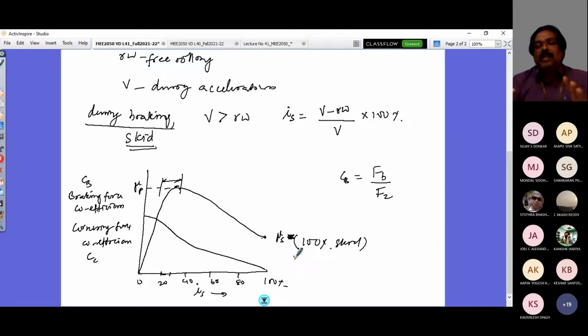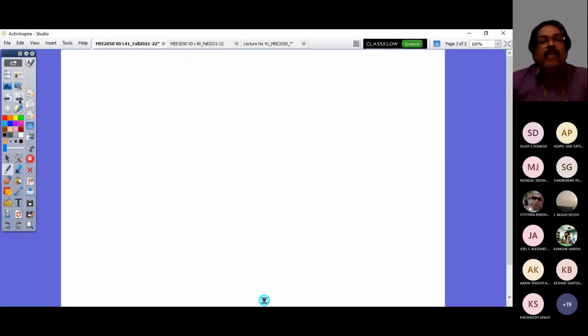So it is very interesting that when I drive my vehicle and I'm accelerating, wheels are having the slip phenomenon, so there would be a forward force, an acceleration. When I apply the braking action, that is decelerating. So when braking force comes, the tractive force disappears on the drive axle. On a non-drive axle, there is only braking force appearing. Of course, there is no tractive effort appearing on the non-driving wheels. These are all important to understand. So for the sake of today's class, let us look closely at the free body diagram of the tire road interaction during braking, the tire dynamics during braking.